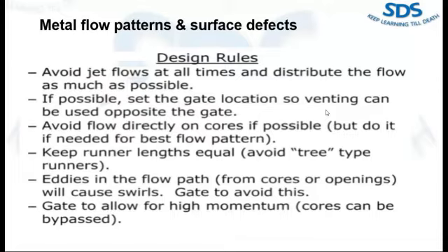It will also help to maintain heat from the gate area towards the screw boss, so that you will avoid shrinkage porosity or flow porosity, and you also minimize the air intrusion, because the best shape to flow any fluid is circular. So when you are designing a round runner, it will help to reduce your air intrusion.